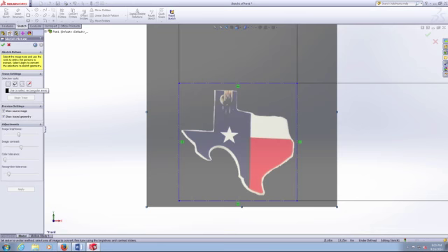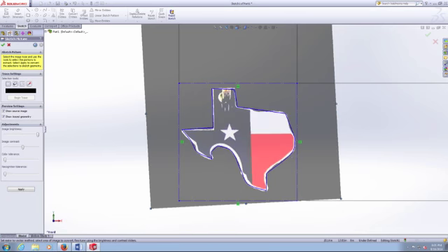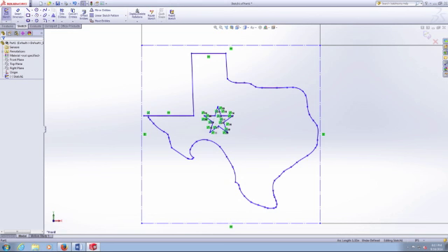The program will begin to generate splines based on contrasting colors in the image. This means that the more distinct the edges of your image are, the more accurate the splines will be. Using the sliders on the left plane, you can adjust how the function reads the contrast in the image. Keep adjusting the settings until you get a spline that you're satisfied with. It does take a lot of trial and error, but eventually you'll be able to find a spline that works for you.